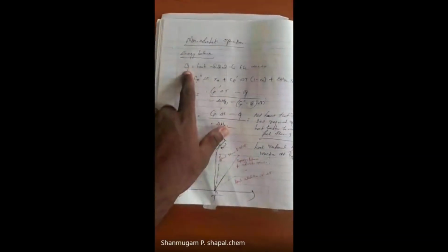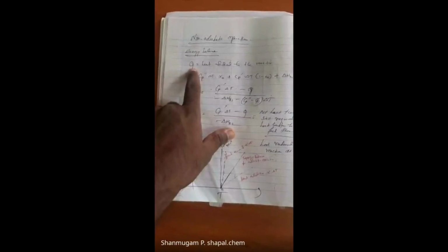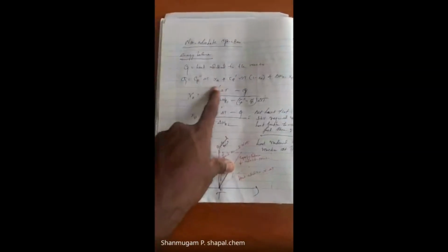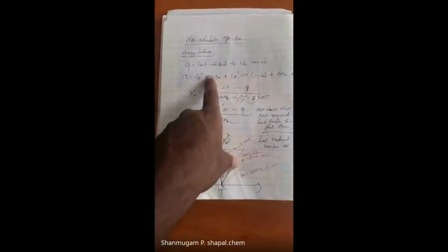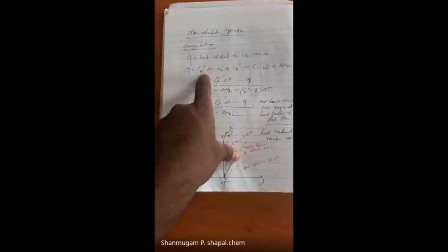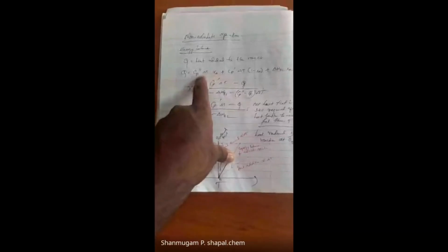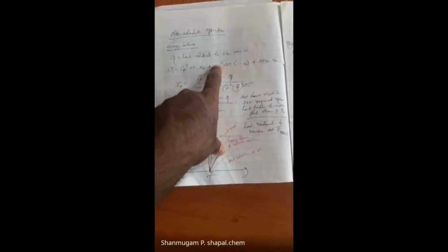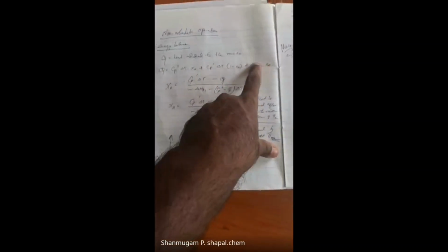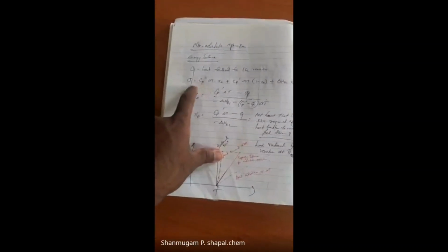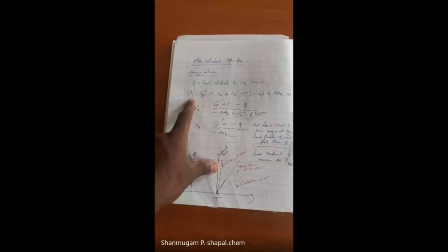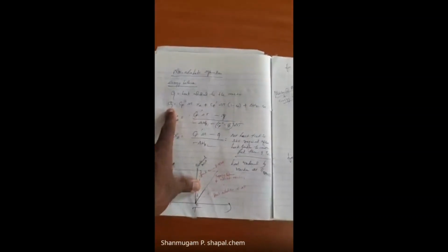we actually have an excess heat that should be added or released into the surroundings, that we need to include. So if you start to write the enthalpy balance, we have the product which is converted, the enthalpy of it, plus the feed enthalpy, plus the heat of the reaction, which is equal to the heat which is being supplied from the surroundings or released into the surroundings. That is, we have to include it.